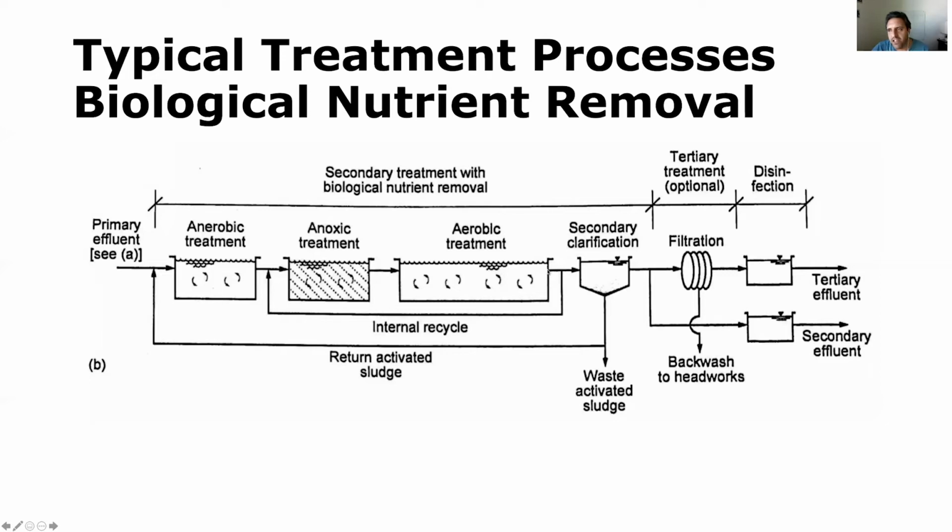In order to convert nitrate into nitrogen gas, we need to have an anoxic or an anaerobic environment so that we can get microorganisms to come in and degrade some of the remaining organic material, and in the absence of oxygen, those organisms would use nitrate for reducing power. So they would use the nitrate kind of to breathe, in a sense. Instead of using oxygen, because they're in an anaerobic environment, they would use the nitrate. That nitrate would get converted to nitrogen gas, which allows it to re-enter the atmosphere.